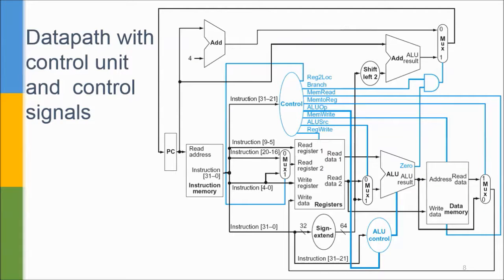...are a truth table for the control unit. It will be useful to try to define the control function informally because the setting of the control lines depends only on the opcode. So each control signal should be 0, 1 or don't care for each of the opcode values.